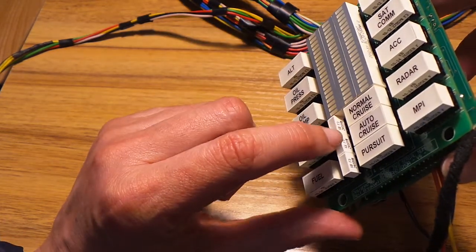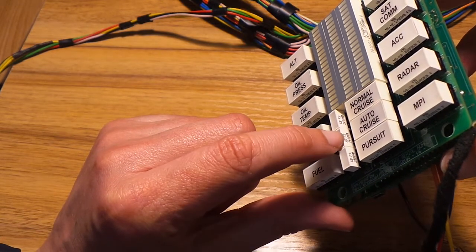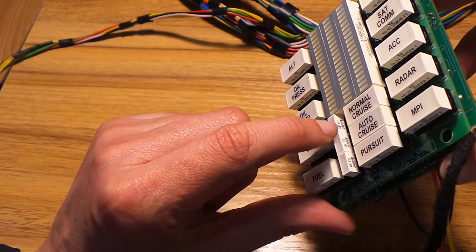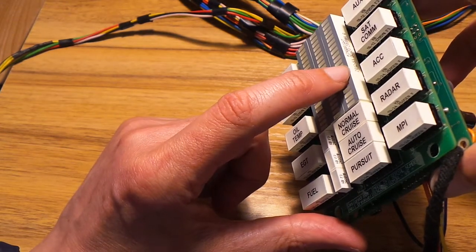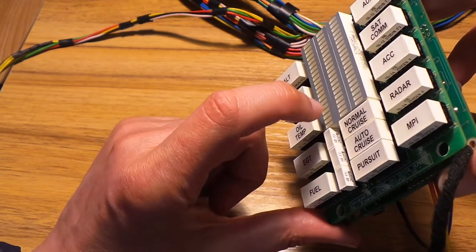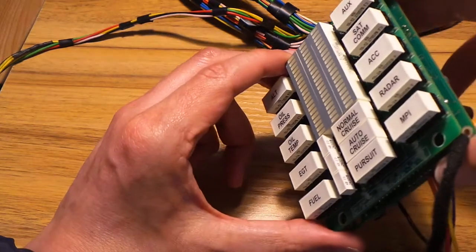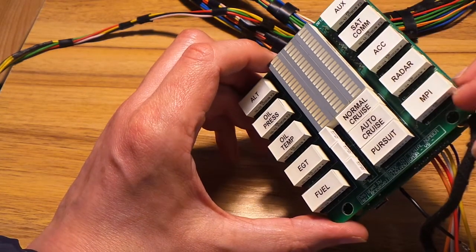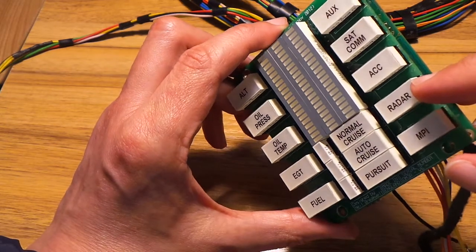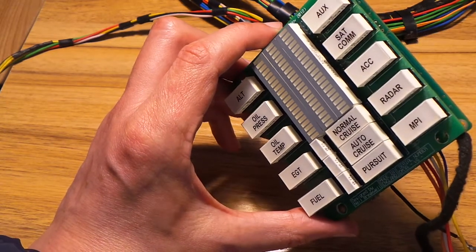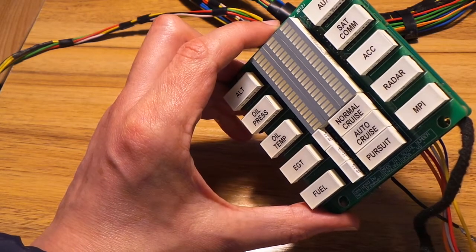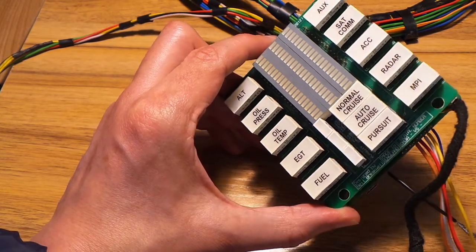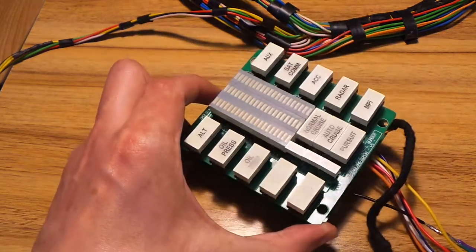And also these LEDs here, the writing, the legend, the print of the part number, is to the right side, as it is on here, and you'll notice on the newer boards, the single boards, the writing is to the left. With these rectangular LEDs, these bigger ones, it doesn't matter which way round the LEDs go. Obviously once you put the legend on it matters, but before you've put the legend on, it doesn't matter where the writing is, they're symmetrical.